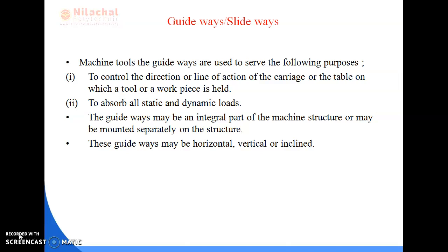Then it is used to absorb all the static and dynamic loads. Means the static loads are the self weight of the workpiece, the tool or the slideways and the forces exerted during the cutting. And dynamic loads means the changing load which is due to the motion or movement of the workpiece.